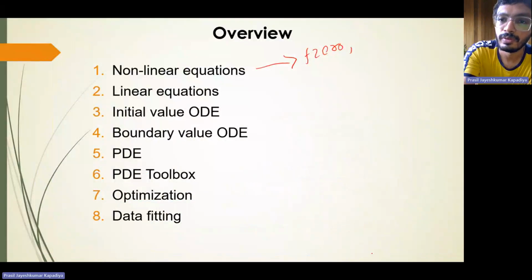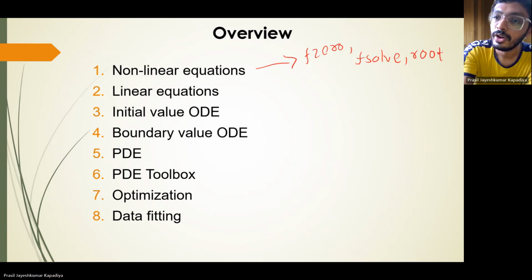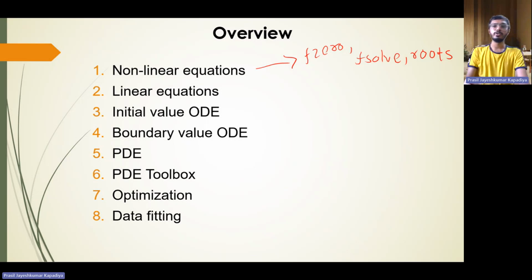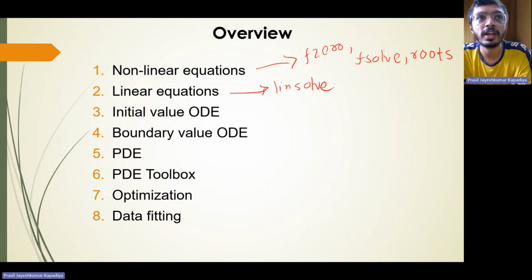When we have a cubic or polynomial kind of equation, we can also use the roots command to solve the equation. Further, we moved ahead with linear equations, and for those we used the linsolve command available in MATLAB. Further, we learned how to determine the rank, determinant of a matrix, eigenvalues, and eigenvectors.